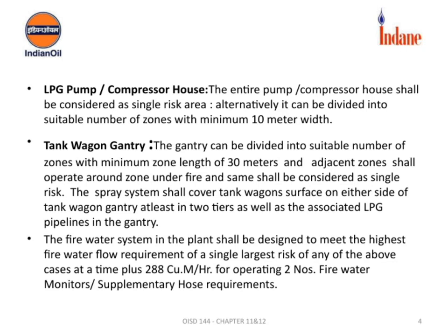Let's take a closer look at the LPG pump and compressor house. This entire area is considered a single risk zone, which simplifies the fire safety planning. However, it can also be divided into smaller zones, each at least 10 meters wide, to better manage fire risks and containment. Moving on to the tank wagon gantry, this structure can be split into multiple zones as well.